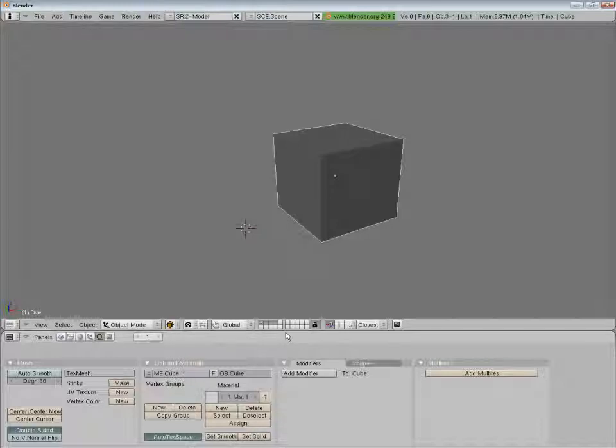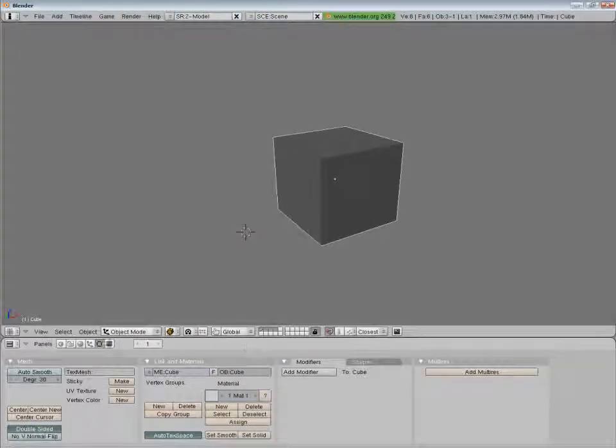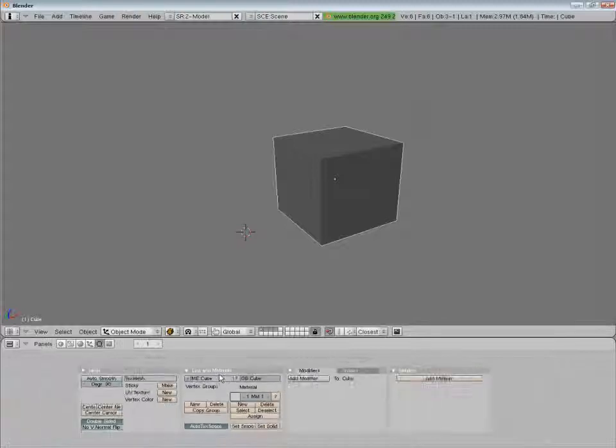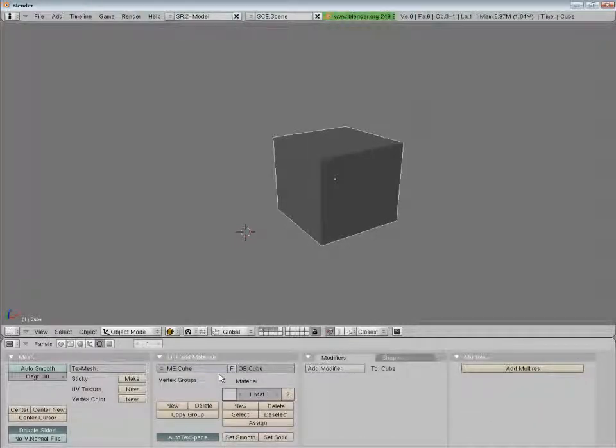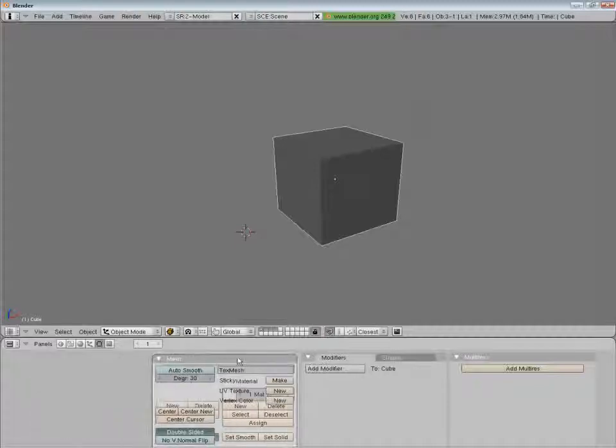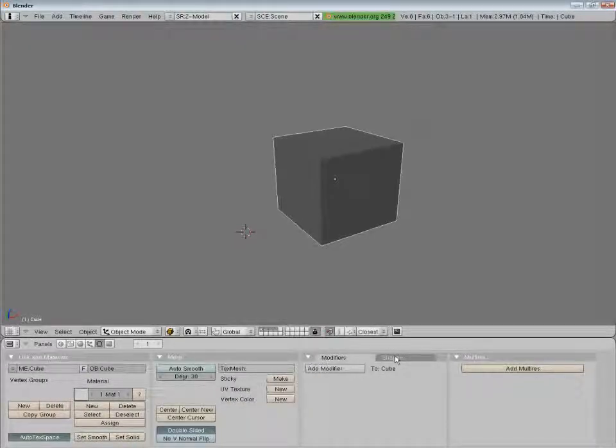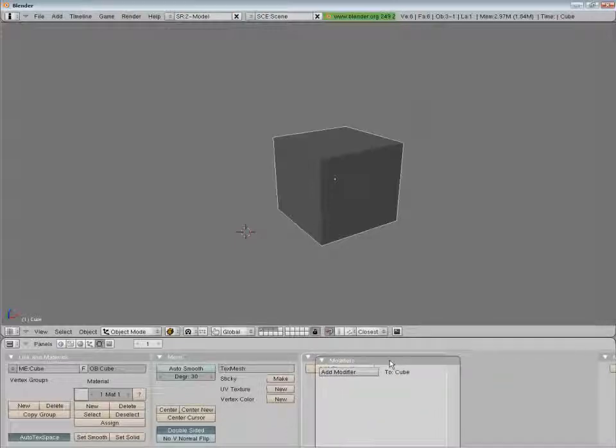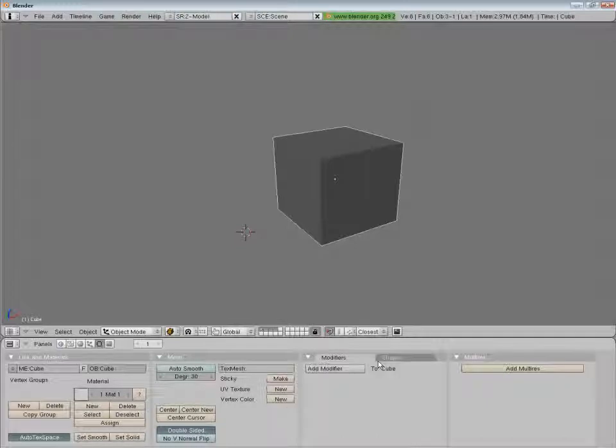Okay, so next chapter is the button window. Here is the option to choose button window type for any window frame. Similar to the 3D viewport, we can zoom in and zoom out with the plus and minus keys of the numpad. We see that buttons are categorized into different panels. These can be dragged and placed anywhere. We also see that two panels are tabbed in one panel. We can detach the panel by dragging it out and place any two or more panels into one. Just place it over any panel and when it gets highlighted, release the mouse. These panels can be arranged horizontally or vertically, or we can also place them freely.